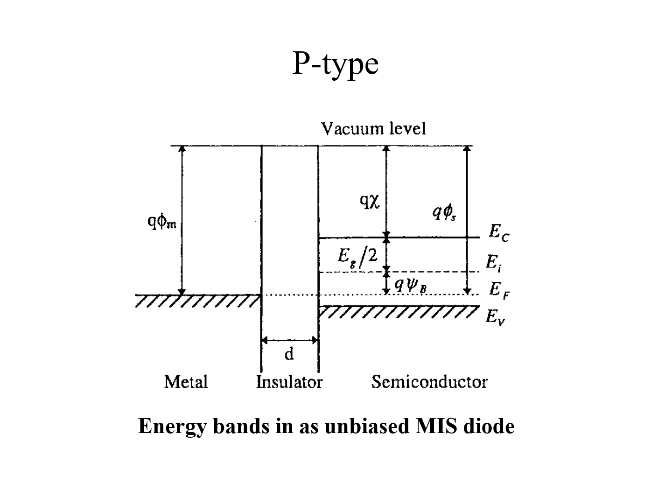You take a metal, so this is the minimum level. So from the minimum level to the maximum level, the vacuum level, denoted by q phi m. This is work function. Similarly, this is insulator. D is the distance between metal and the semiconductor. Okay, so this is the level of valence band. The dotted line represents the Fermi level.